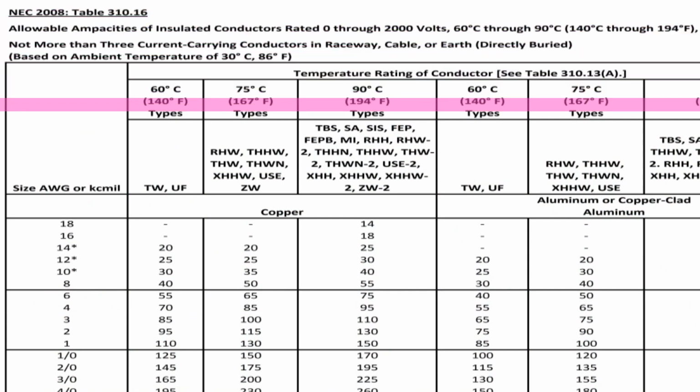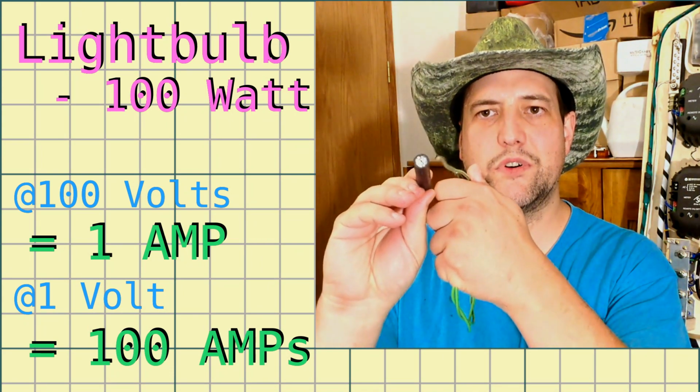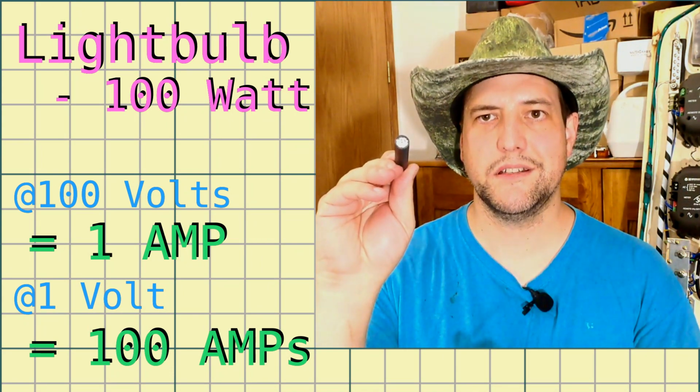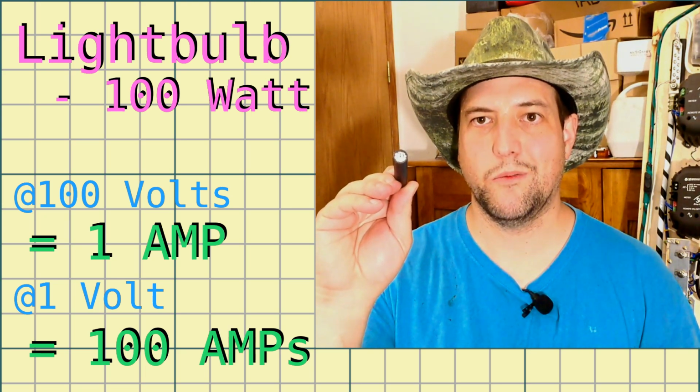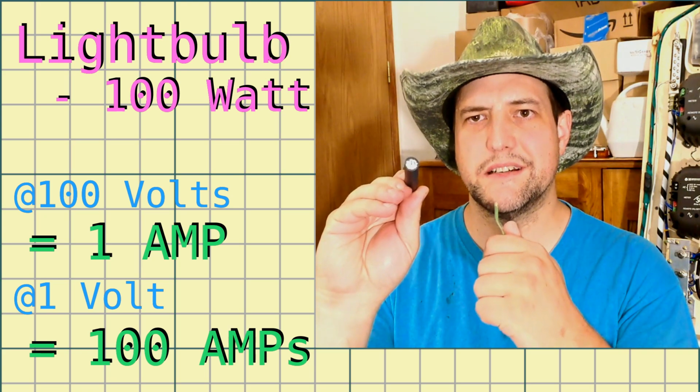100 amps. Go down the chart, go down the chart. Wow, that's a bigger cable, isn't it? Let's take a look at an example cable that could do that. This is 2 gauge. 14 gauge will do it for the first one, but this one we need something much bigger. We got a difference here, don't we?